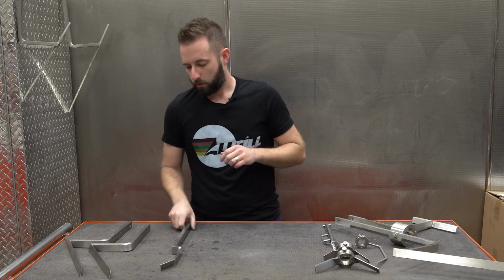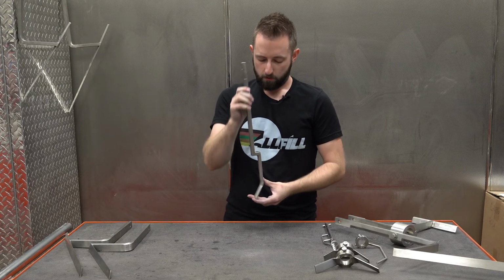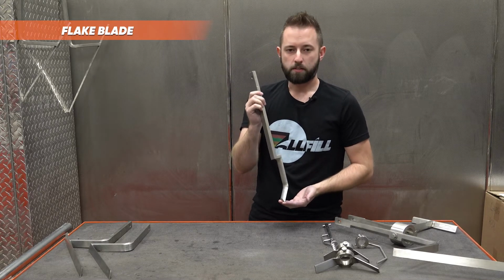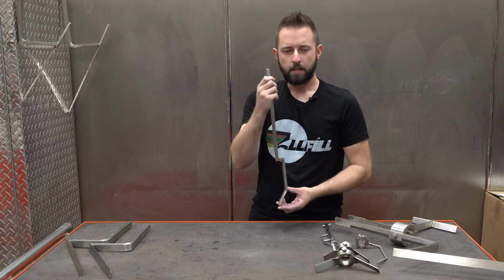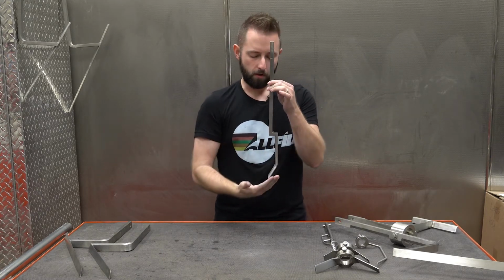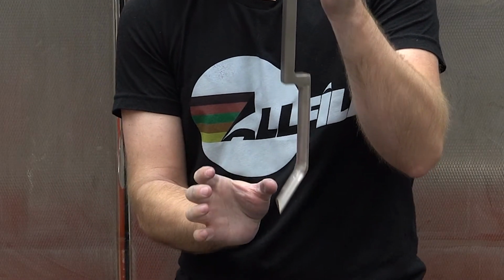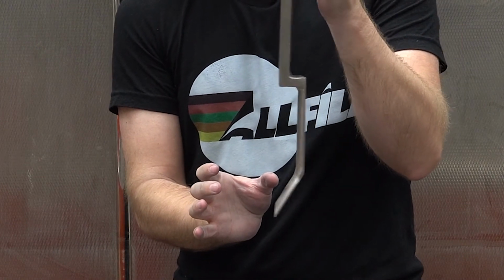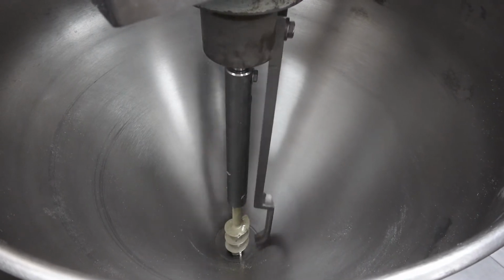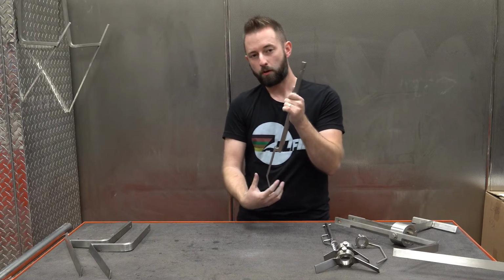Which brings us to our third type of slow speed agitation blade. This is what we call a flake blade. So this is very, very helpful for leafy products like thyme, parsley, light density spices. And essentially what this does is, instead of following the profile of the hopper, this is more targeted agitation. So the outside diameter of the overflight would be right about here. And now this hugs it very tightly. So this is causing any product that is around that overflight, directly in that area, to collapse, and it's helping eliminate that rat holing issue we were talking about.